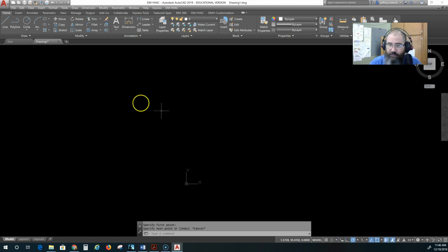So let's turn off dynamic input and see how this works. So I'm going to place a line, and now moving the line, you can see down in my status bar it's showing the coordinates that I want right there. Now I can type coordinates. Right now it's going strictly by coordinate system. It's not going by any other relative coordinates or anything of that nature. So if you look down at the bottom, it says 9 point something and then 11 point something.